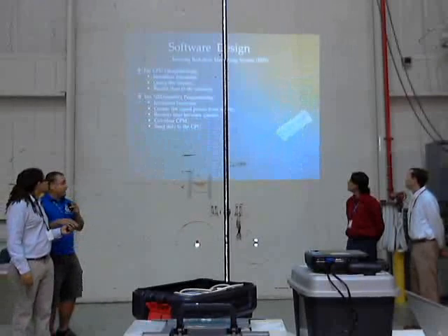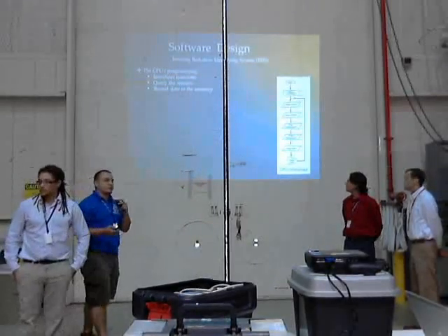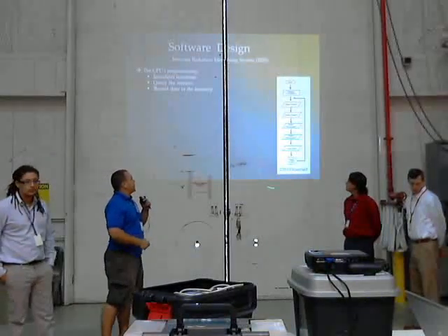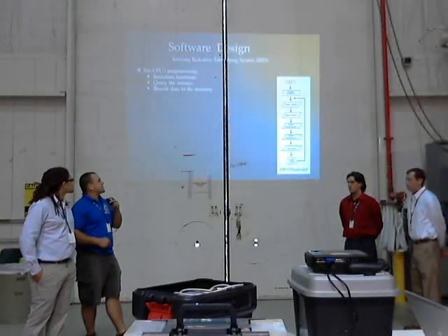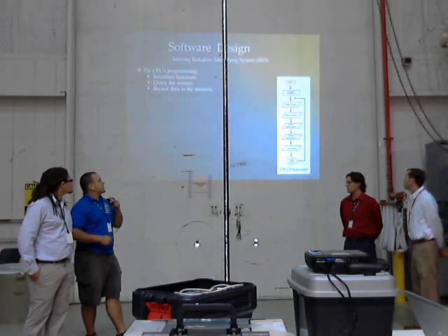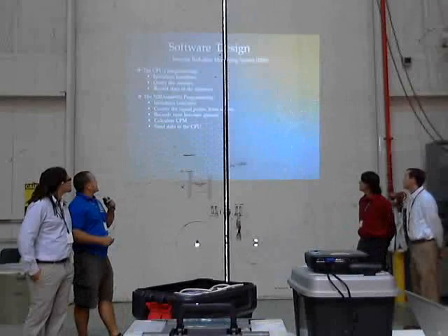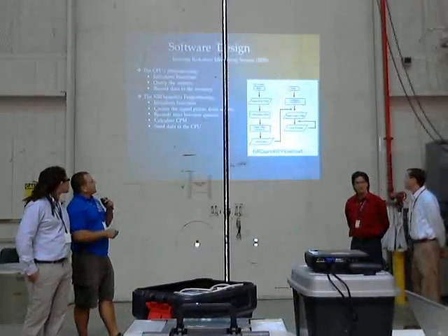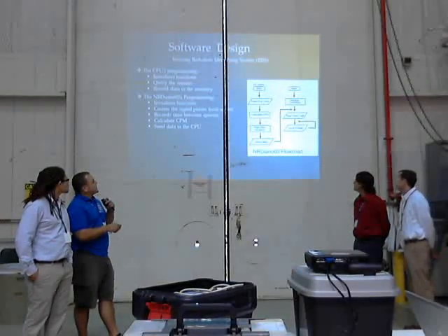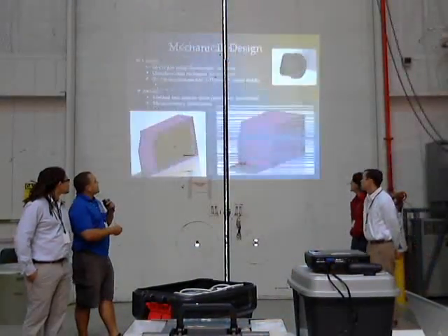All right, the IRIS uses 3 different microcontrollers, each programmed with their own software. The CPU is going to be programmed with a very simple, basic program where it goes through, queries all the sensors, saves the data, and repeats itself. It's going to do this once a minute. For the sensor Arduinos, it's going to count the pulses on an I2C query event. The second one's going to be very similar.